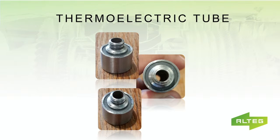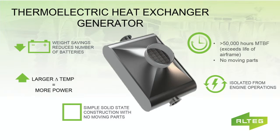And each one of these modules at a 200-degree temperature delta between the hot side, or the inside, and the outside can produce 1 watt. At optimum power output, it can produce about 2.5 watts. So if you take all those and put them together in series, now you can create a tube and shell type heat exchanger. Anything that goes through the interior of the tubes, that is your hot side. Everything that goes through the outside of the tubes, that's your cold side. And if you put those tubes together in series electrically and thermally in parallel, now you can generate a ton of electrical power.